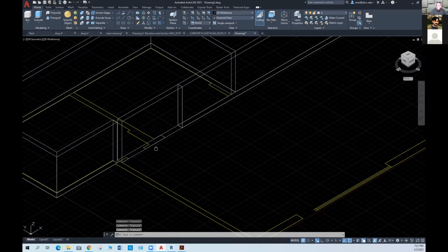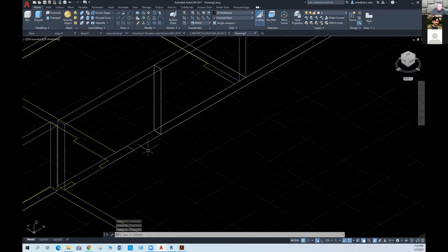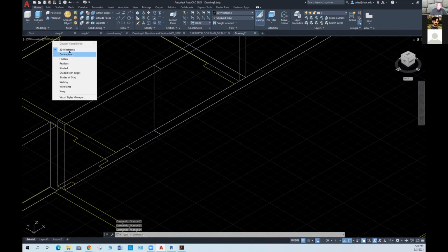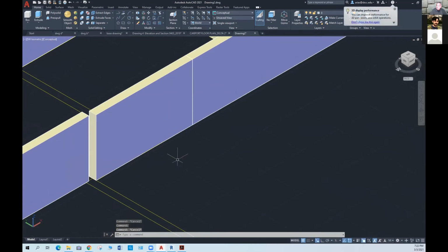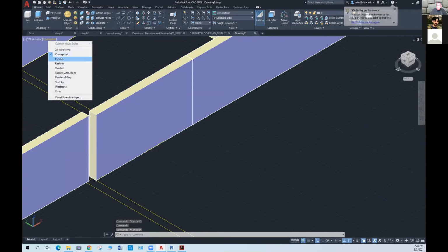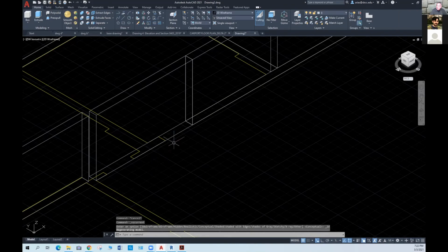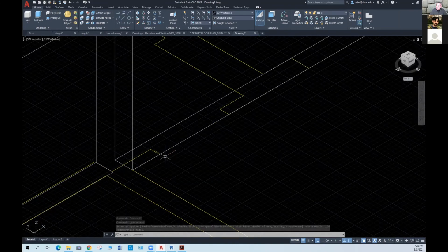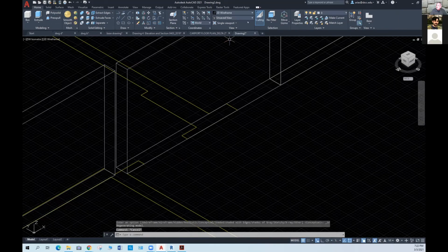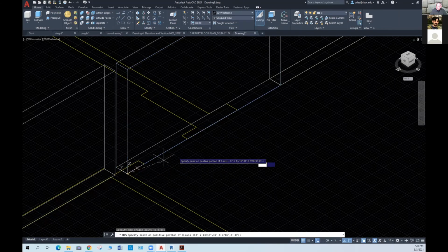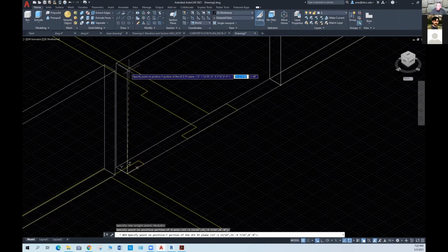We could create these openings by using some of the tools that we have already reviewed. So the first thing I'm going to do, we're going to go to 2D wireframe, and I want to create this door. I know that the door is going to be this width by 80 inches. So the first thing I do is select 3-point UCS, click here for 0, X, and Y.